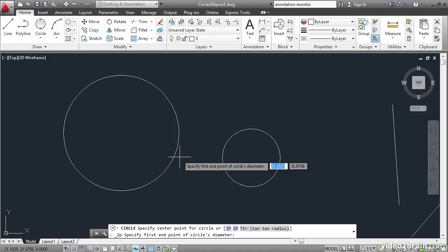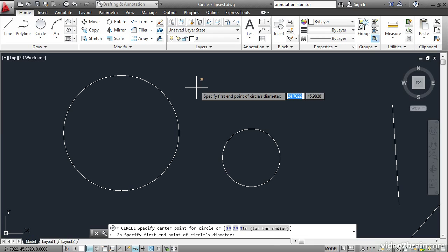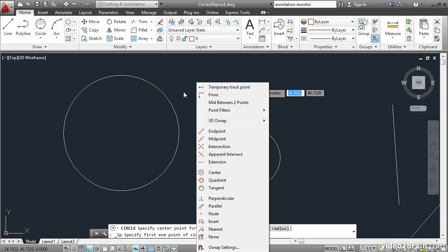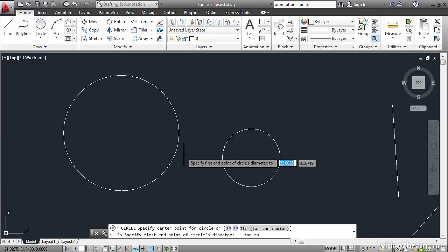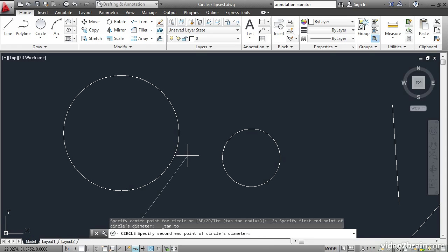To do this, I'm going to use Object Snap so that we can precisely connect the circle to the other two circles. Hold down the Shift key and right-click to open the Object Snap context menu. Select Tangent from the list. Position the cursor over the larger circle and you'll see a green symbol appear which indicates tangency. The tooltip says Deferred Tangent. I'll click here, and AutoCAD isn't exactly sure where that tangent will be yet. It needs more information. That's why the tangent is deferred.